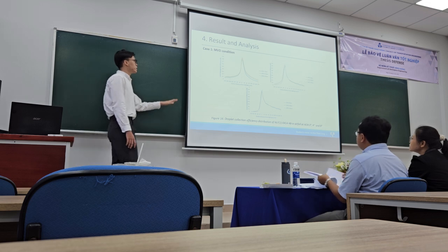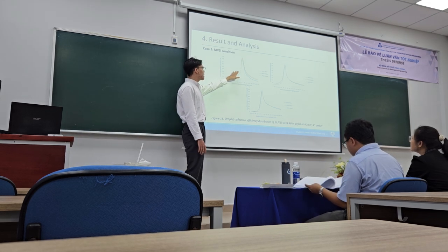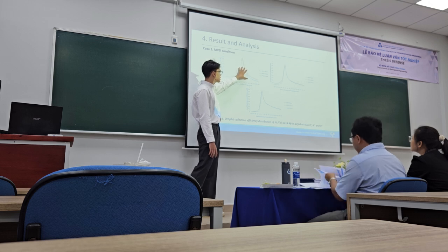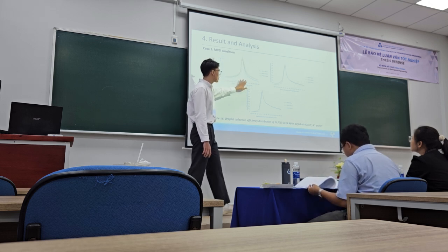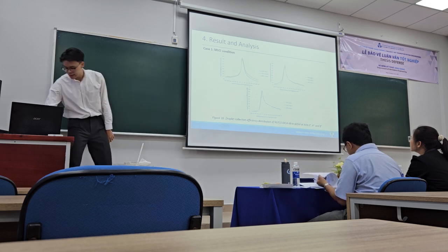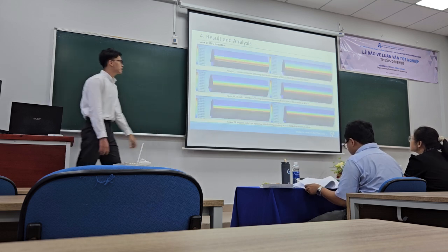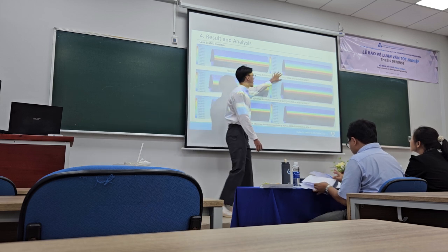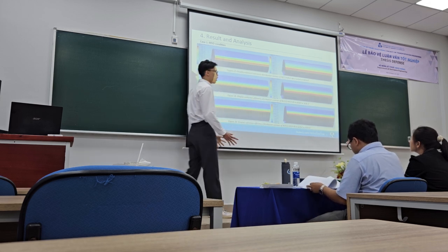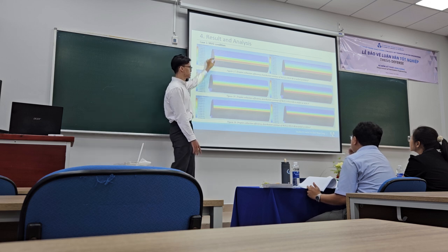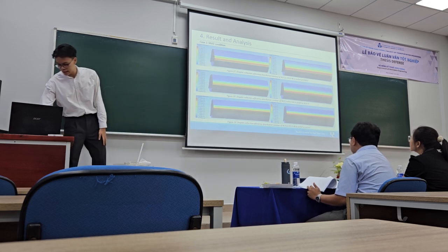As you can see on the screen, if the medium volume diameter increases, the beta collection efficiency also increases. This is for 0, 4 degree and 8 degree. And you can see clearly on the contour that with the higher volume diameter, there is a higher range of collection efficiency on the airfoil surface. And this is for 2D wings.